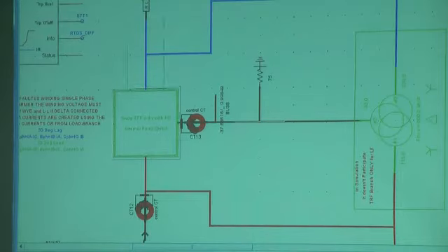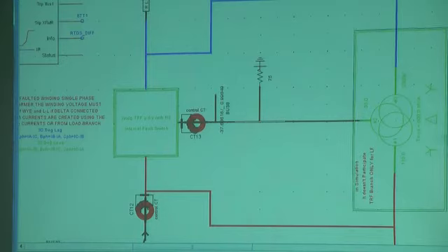Because these are single-phase, non-load flow, we have an artificial load flow branch here that encapsulates the single phase, and all this is used for is to provide the right inductance and MVA and winding voltages to help solve the load flow.